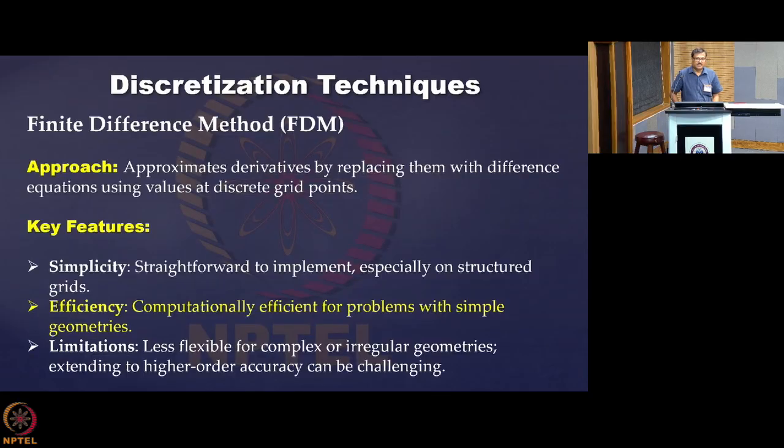So now coming to the fluid dynamic equations, how to solve them actually. First you need to discretize the differential equation that governs your system. Now I don't know whether you already know about these discretization techniques. There are three major schemes which people use. One is the finite difference technique, one is the finite volume technique, and one is the finite element technique. I will just give you a flavor of how these techniques go as far as discretization is concerned.